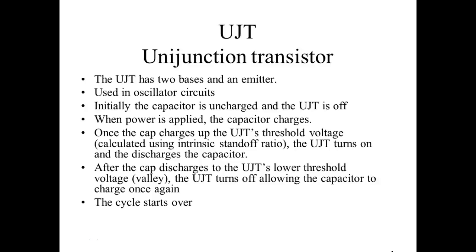So this guy right here operates off of DC. We bring in AC, we have power supplies in it, and I think we actually showed y'all this taken apart. It's got a power supply that creates a plus and minus supply, and then it's got oscillator circuits in it that we can control the frequency of. So what is it doing? It's taking AC, converting it to DC, and converting it back into what? AC. So anytime I have a circuit that converts DC back into AC, we have to go through what circuit? Some type of oscillator that electronically generates a frequency from DC.